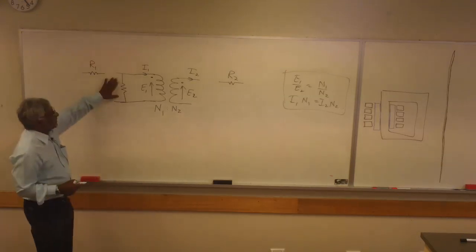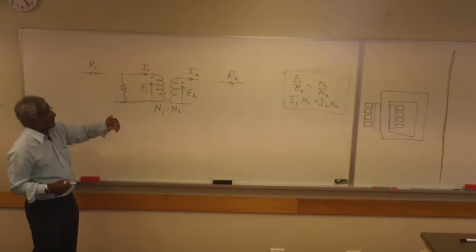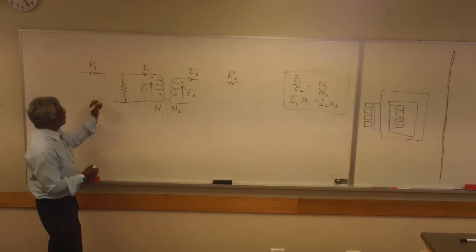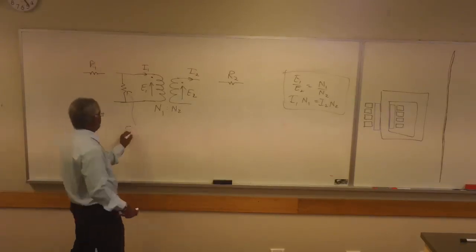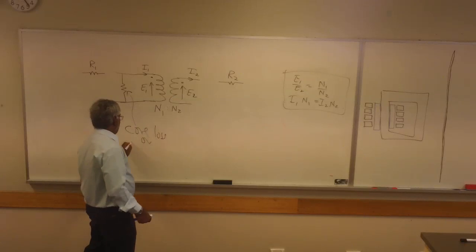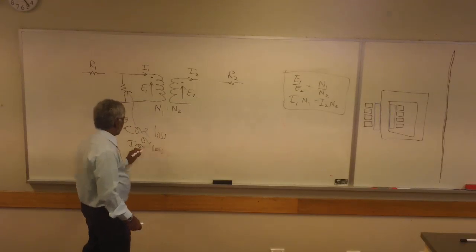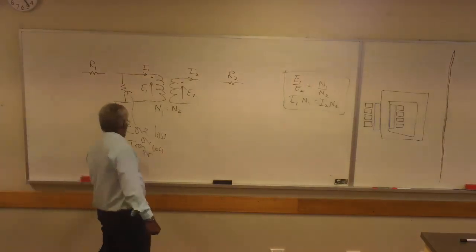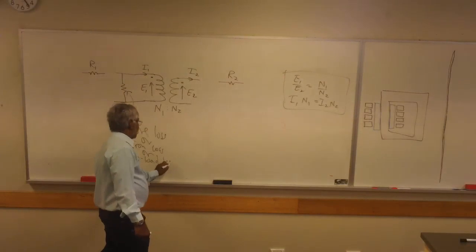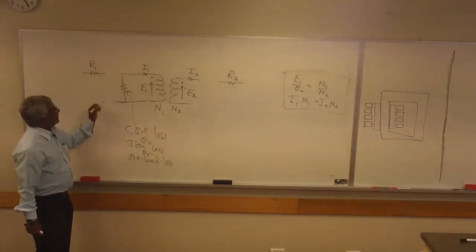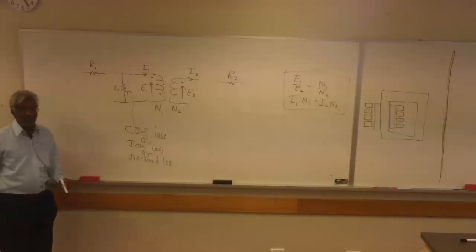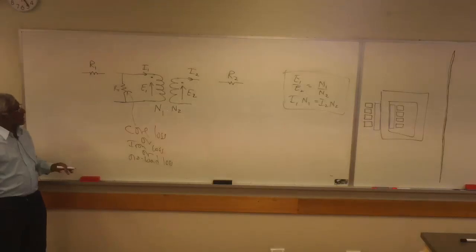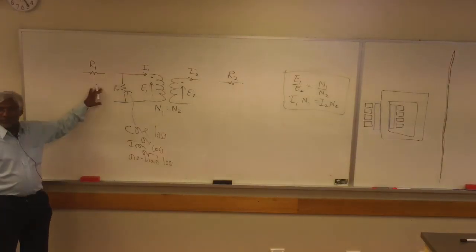For now, we'll just say that there is some core loss, which is made up of hysteresis and eddy current. So we say core loss or iron loss. So that's represented by this, core loss or iron loss. There is another name people use, which is called no-load loss. So all these mean the same thing. And this resistance is normally called R0. So that's another imperfection. Any questions about the core loss?